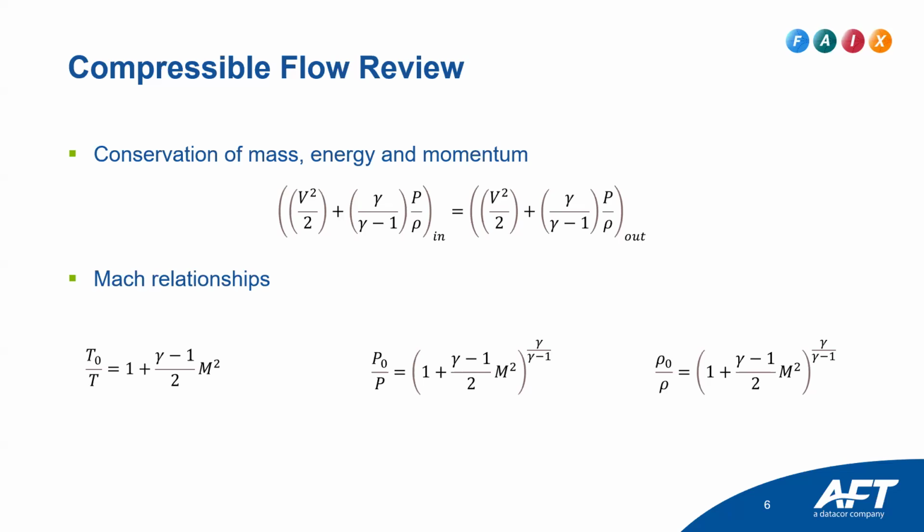Static temperature, does this mean the temperature in the steady state condition? No, the static temperature is essentially the actual temperature. The stagnation temperature is, if you imagine the tip of a wing, where the flow stagnates at the very tip of the wing, it's hotter than it is in the bulk flow. That's stagnation temperature.